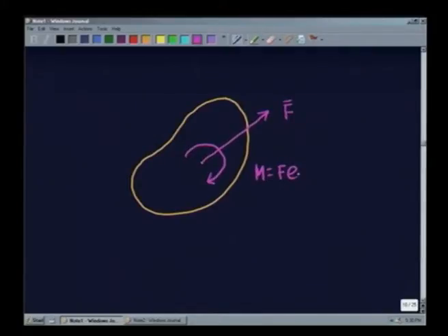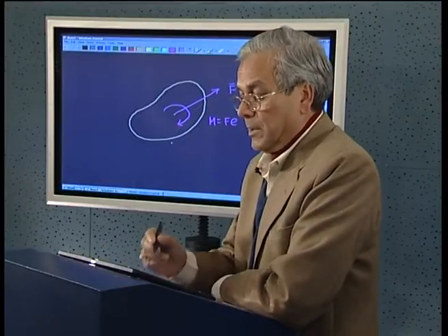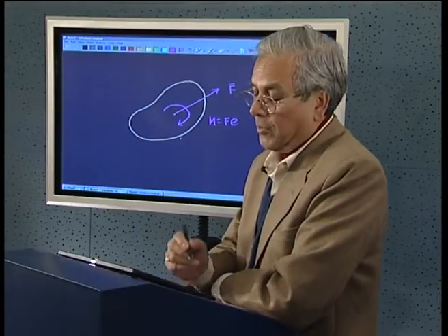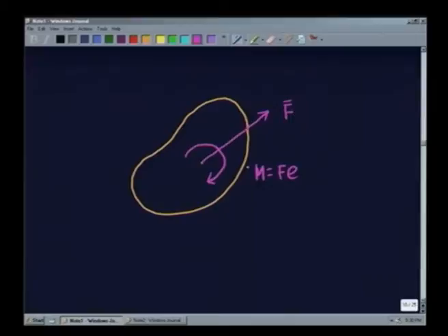Now, you will notice that I have not put a moment vector here, because in plane motion all angular quantities, like angular velocity, angular displacement, moment, can be represented by algebraic quantities. Say we may consider that if it is in the clockwise direction they are positive, if anti-clockwise they are negative. So, their summing up or subtraction is just like an algebraic quantity, whereas force has different directions and so needs to be represented by a vector.